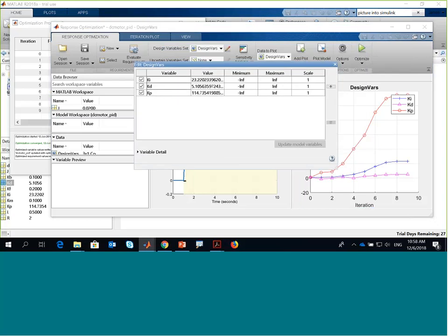So just now what I did was I put it from minus infinity to infinity. This algorithm runs through all the possible values from minus infinity to infinity, and this will definitely make your optimization slower, and it might give you the wrong answer also. So if, as an engineer, you know your values, for example Ki, I know that it cannot go below 0, so you just set it here to make the optimization process easier so that it can run faster. But in terms of the iterations, where do you set it?